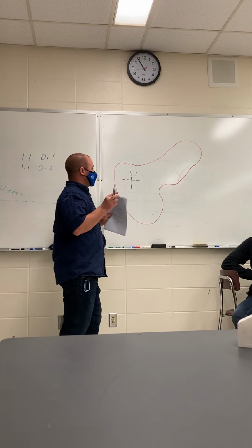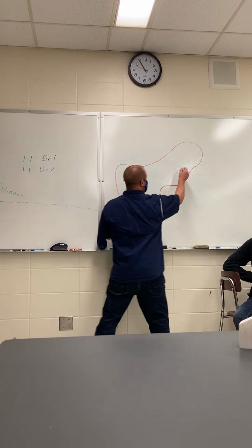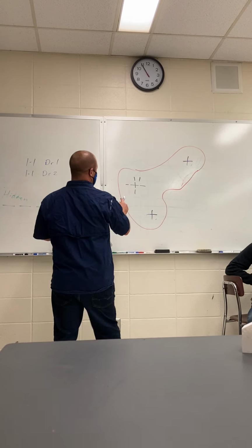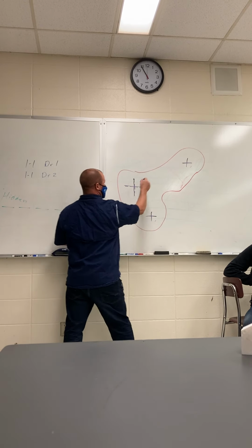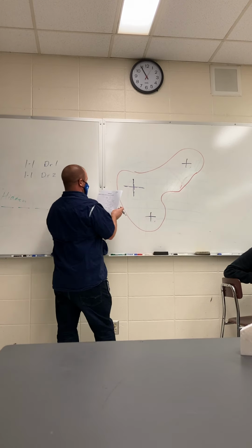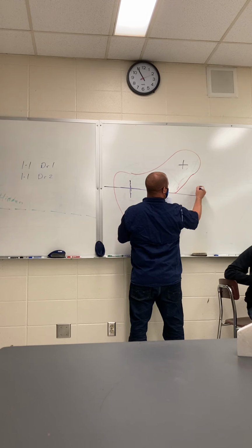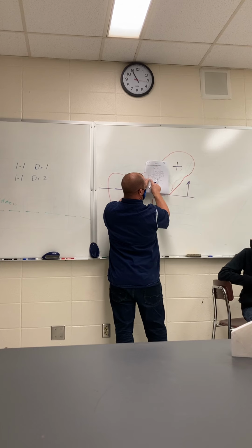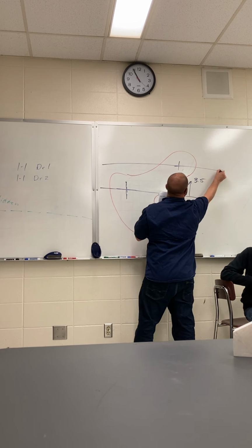When do I see you? Monday? I'm gonna go through this in further depth, but what you need to do is locate these three center points. Trim them off and make them look about like what I got right here, okay? I would do this one first, but it doesn't really matter which of the three you do first, because off of that you can derive it however you want. Because all you do is you take a line here and you use offset. And you go up, if we look on this dimension over here on the left, up 3.5. We're gonna go up 3.5, that's gonna create a line here.